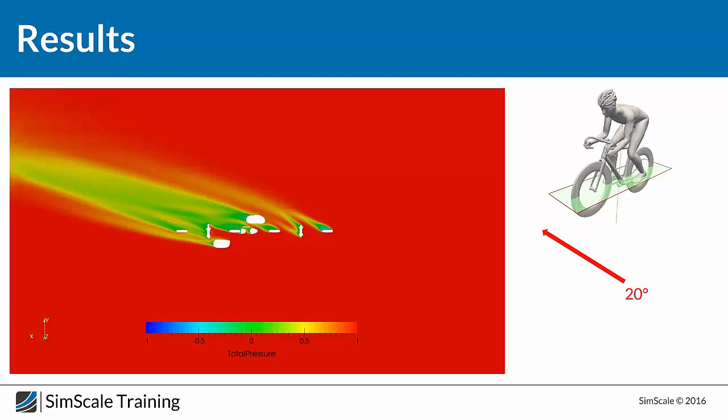Like any application, when you talk about performance, performance is related to the operating condition. So, like I told you before, and we will show this when we talk about the graphs and the forces, this tire is really, really efficient when you don't have a side wind. So for a competition with a closed circuit, where you don't have a side wind, this tire can make the difference in terms of performance, because the drag of these tires is really low compared to the others, but the side wind effect is really significant. Okay, so let's jump to the next.